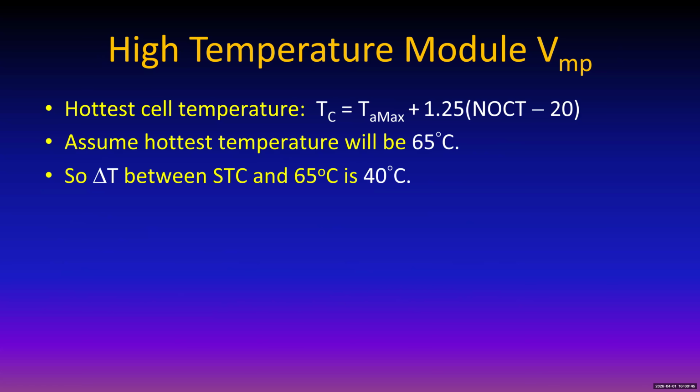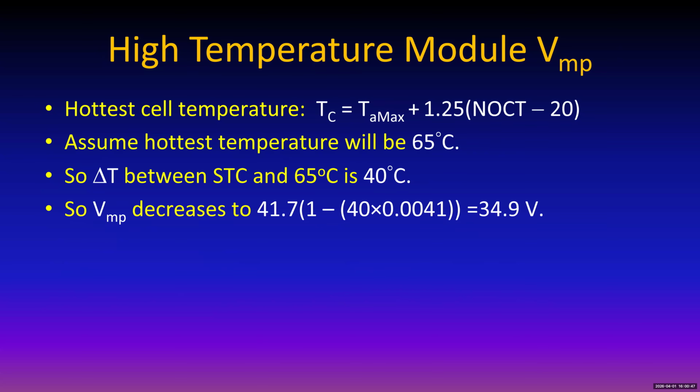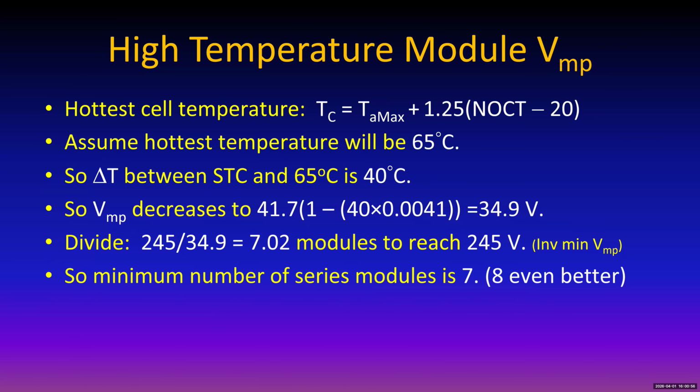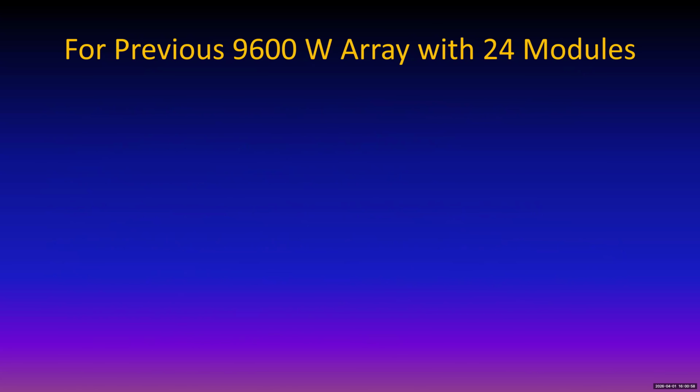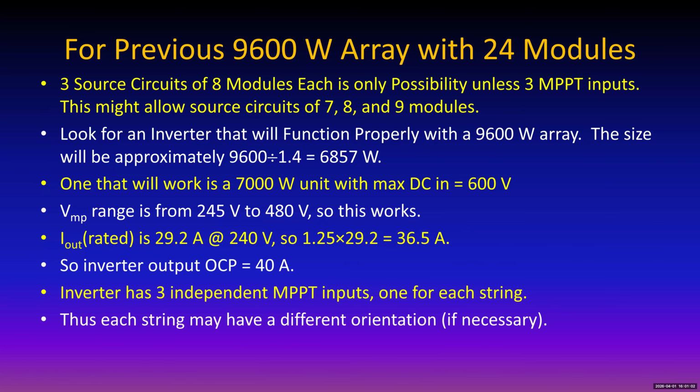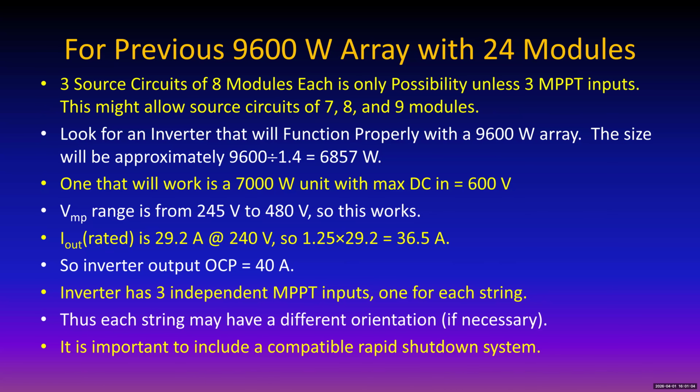Hottest cell temperature, it's easy to calculate. How hot is this? What's the lowest voltage this thing's going to operate at? We need to know the highest and the lowest in order to determine the string lengths, okay? So here we go. Again, don't try to read this fast. It's there in case you need it.